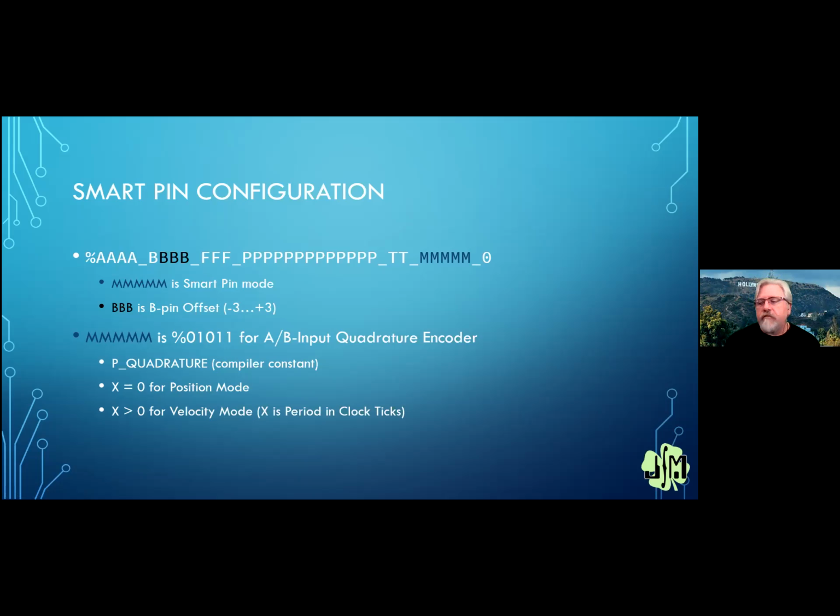And this is really nice. Again, for the project I'm trying to wrap up today with my friend John, we have this Quadrature encoder where we need to know position, because this is moving a device, but we also need to know how fast it's moving at any given time. So I had to write in Spin1 code an assembly cog that could do the normal Quadrature stuff like you saw, but also in that code I had to look for when changes happened and look at delta timing of the count register to get those changes. So it was a bit of work. It does work, but this makes it so much easier. If we ported that project to the P2, we wouldn't need an encoder cog anymore. We would just use 2 smart pins, the A and the B. We would set up A for our position, and we would set up the B for velocity, and we would be done.